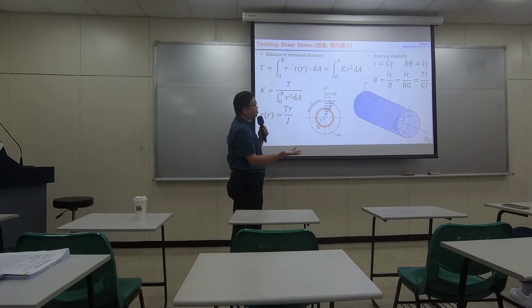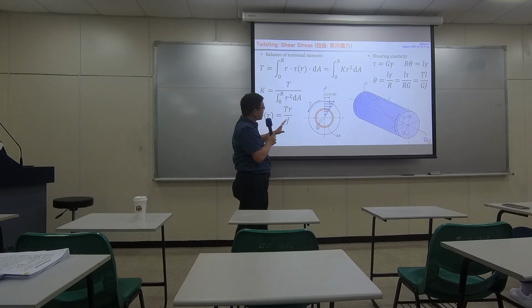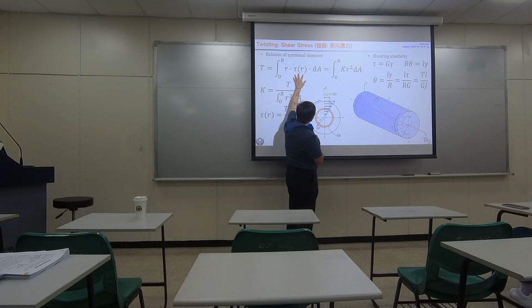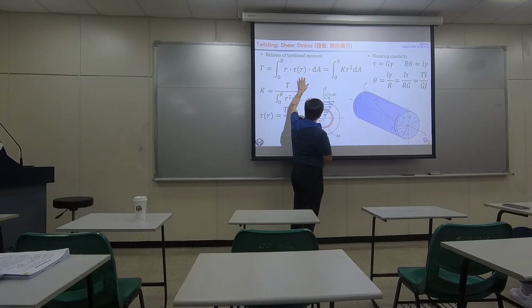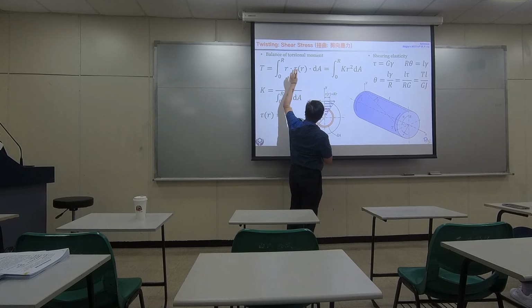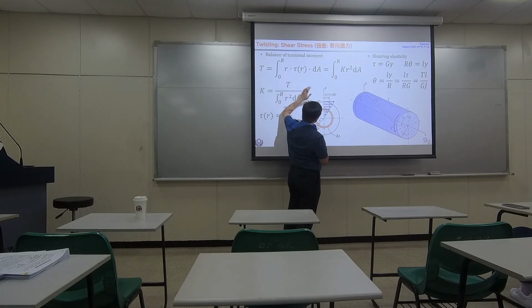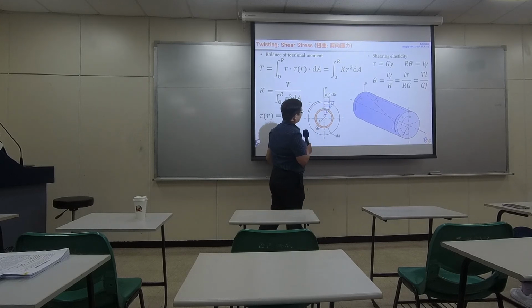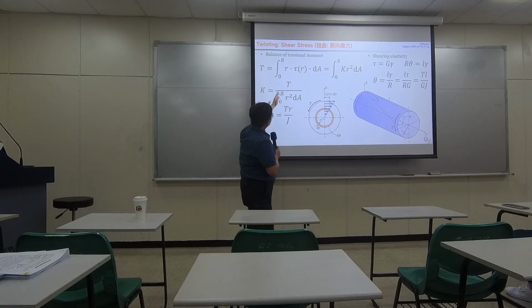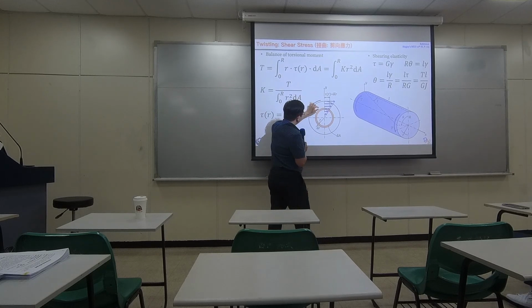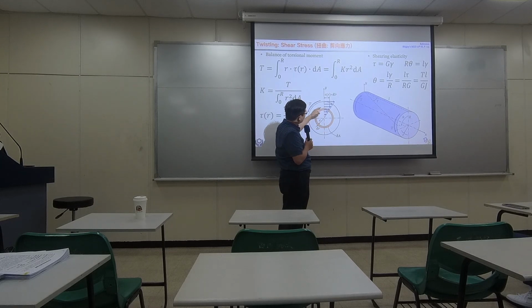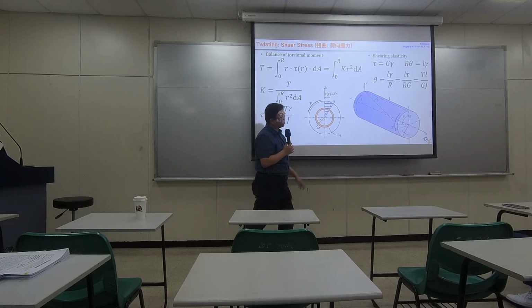So basically same trick. The only difference is that the geometry is different from the previous page. This is stress times area, the force surrounding this ring, multiplying radius, that's the moment surrounding this level. So this only gives you the moment contributed by the force applying on this ring.